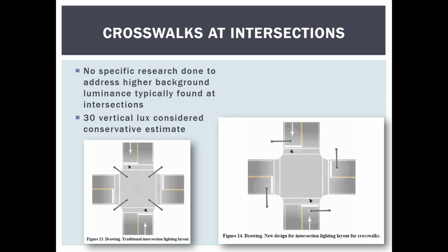When you have like 3 lanes in each direction plus dual left turn lanes, you're going to see a wider area. But the intent is to provide light on the front of the pedestrian as a higher speed vehicle is approaching the intersection. Whereas in the example on the right, if you're talking about a turning vehicle, the concept is that it's supposed to light the area up, and they're already going at a slower speed where they can see and detect the pedestrian. The vehicle headlights can work better. When you get to higher speed conditions, the vehicle headlights stop working.